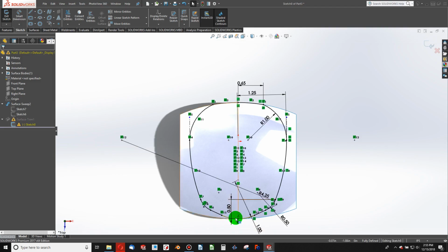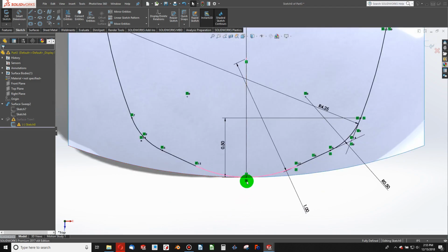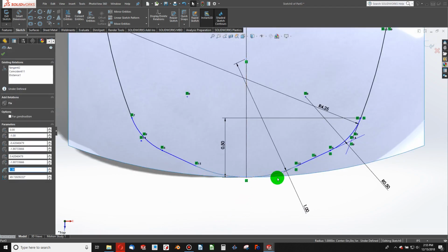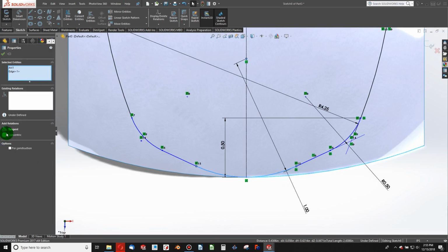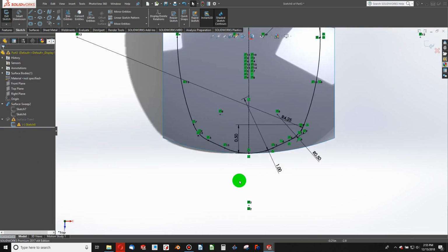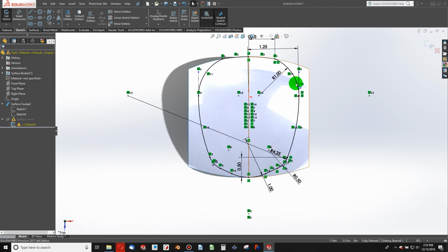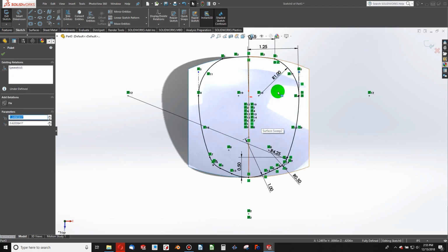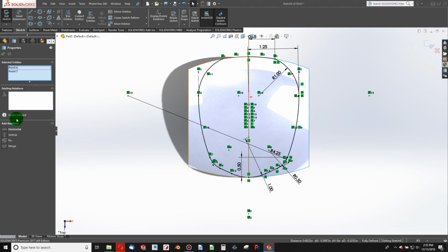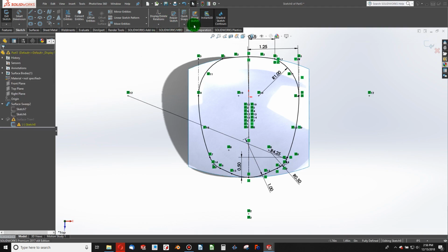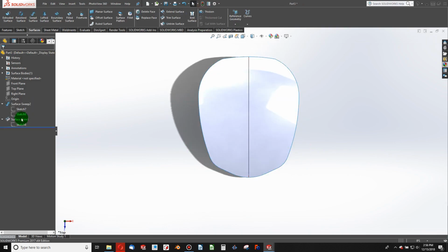And we're fully defined again. And I have the same case down here. And we're fully defined. So if I have any conflicts with sketches, I simply re-add the lost constraints in an update. Now I'll rebuild, and we have no more rebuild errors.